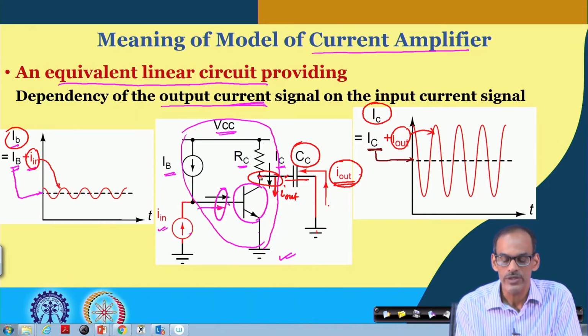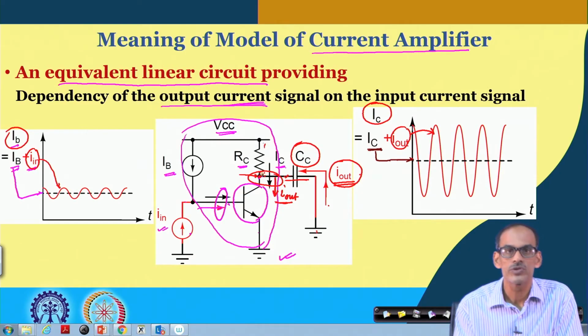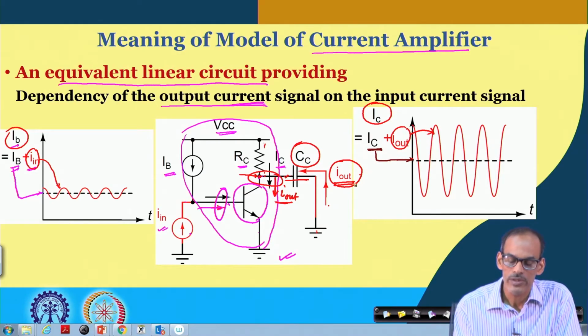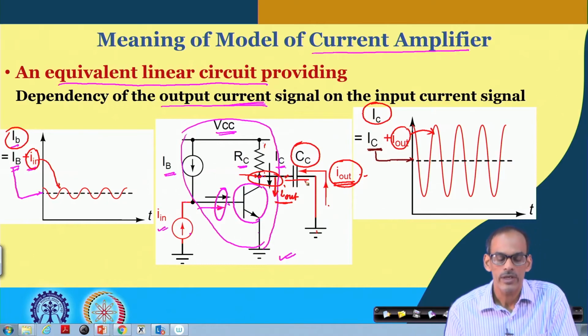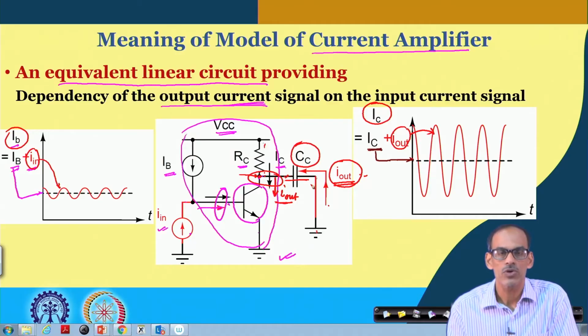So, naturally the voltage here, ideally, by making this connection will not change, and the signal current that is flowing will not flow through this resistor. The current we obtain here is referred to as the short circuit current, or unloaded current. I must say it is unloaded current, since the signal here is in current form. So, to get the entire current you must short this to AC ground.